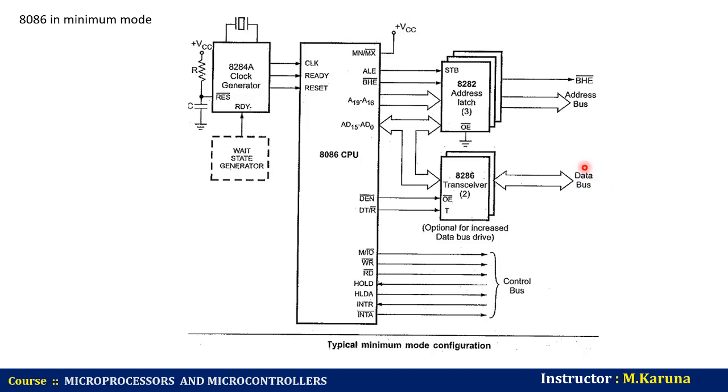These latches are buffered output D-type flip-flops. These are used for separating the valid address from the multiplexed address and data signals, and are controlled by the ALE signal generated by the 8086 microprocessor.